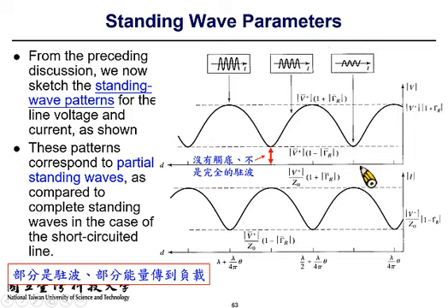So what is the significance of this result? This result shows that some of the energy is reflected back while some of the energy goes into the termination, goes into the load. The component that goes into the load is referred to as the traveling wave. Traveling wave is the energy that can travel along the transmission line and be delivered. The reflected part, together with the corresponding incident energy, forms the so-called standing wave.